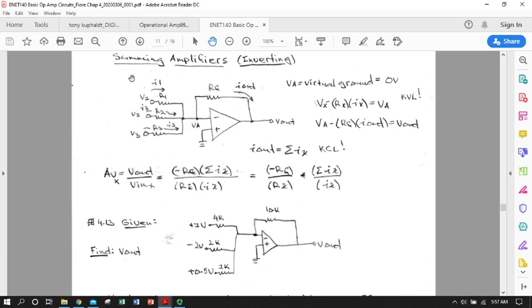A thing to remember when we're talking about voltage signals, we're not talking about just increasing voltage, say for power purposes. These voltage signals are information signals. They're coming from an instrument or something, so you want to retain their specific frequency, phase, and other characteristics that carry the information. So when we talk about summing them, we want to know how we would add these signals with respect to their total amplitude, phase, frequency relationships. Everything like that has to be retained. And that's one of the reasons we use these types of circuits.